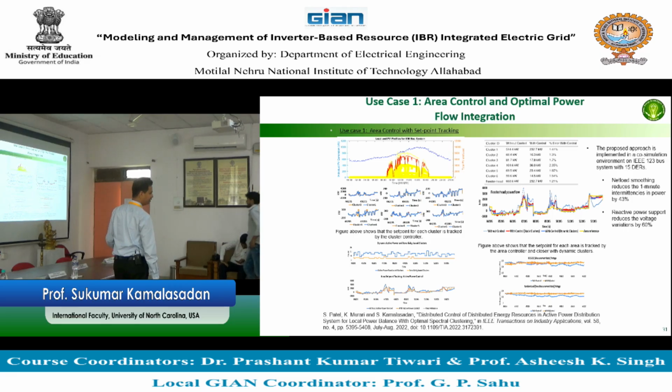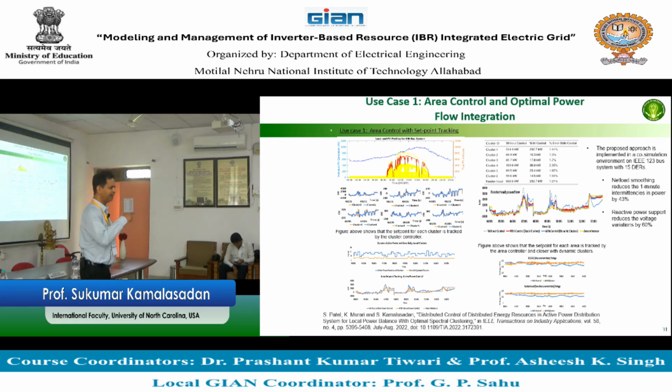Oh, this is another interesting thing. Here, instead of a constant number, we are asking the distribution network to follow a pattern. Right? This can be ancillary service. So I am not asking the distribution network for a flat line. I'm saying flat line is good, but on top of that, give me this shape. That shape is supporting the frequency or something else. And you can see that that shape is honored, but in some places that is not honored. You see, it's going up. But with the controller, this blue dot is without. With the controller, you are actually able to track that closely. Yes.